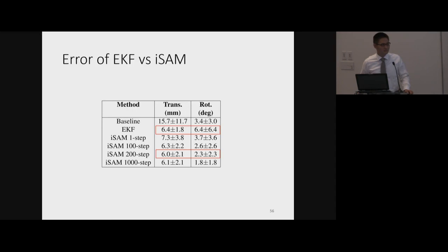So maybe just to clarify the question, what John was asking is whether the state estimator would remain stable, independently of what the object does. Would the state estimator have drift or diverge without looking at it? Even fusing the vision and the touch. Imagine if you had 2 fingers in a square, and you're just going back and forth. I think with vision it should be pretty okay because every time you can relocalize it, and that's why we want to add this vision. Like imagine the car going through a tunnel, and after going out, it sees the GPS and it can know where it is, not exactly, probably roughly where it is.